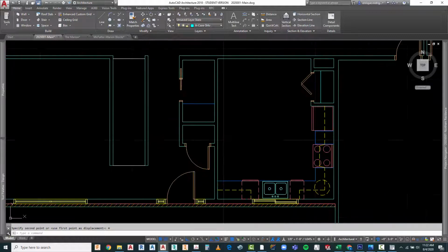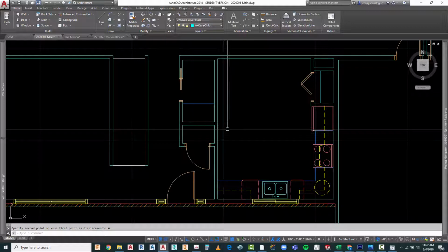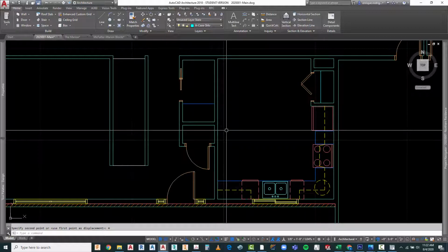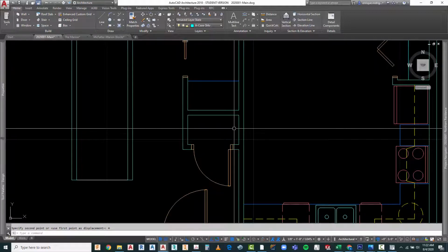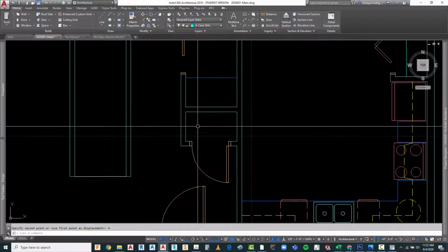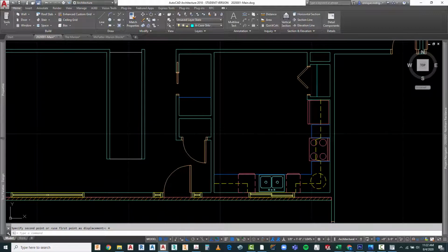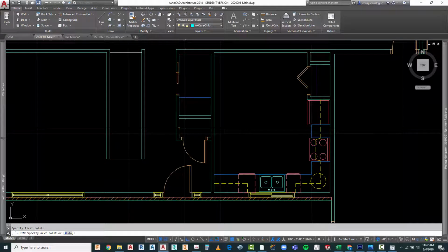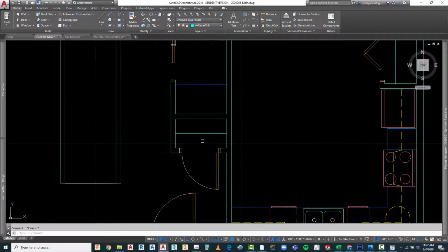Alright, looks like we've also got shelving, and if you notice on the markups they have S and P. Well, that's old school. What it meant was shelf and a pole. So you would have a shelf and then a horizontal wooden pole across to hang your clothes on. Nowadays there's all sorts of closet systems that go into it. So for now, with the AK shelving layer, I'm going to go ahead and indicate one line across. That's going to represent nothing but shelving.